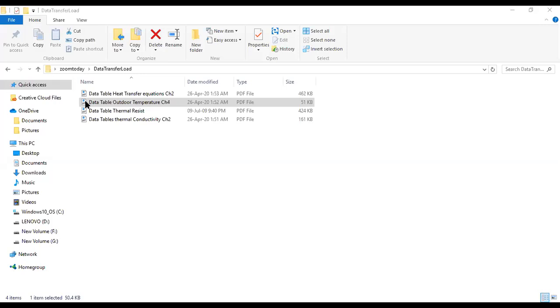These are design temperatures. You know, this is for winter. You will take this outdoor temperature TO for calculation of transfer load. This is TO for winter. This is TO for summer. And this is the design day average. So this is how we use this table.